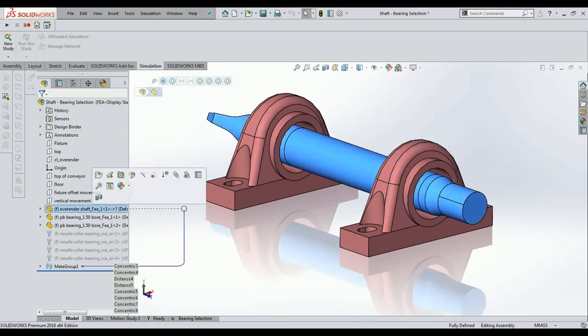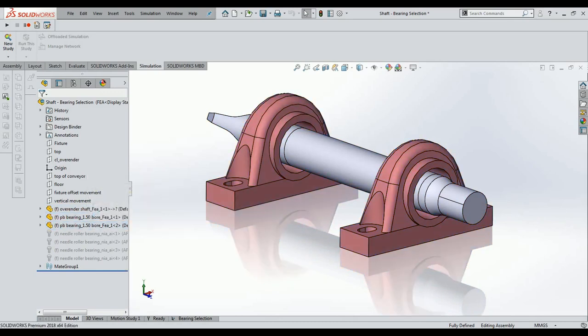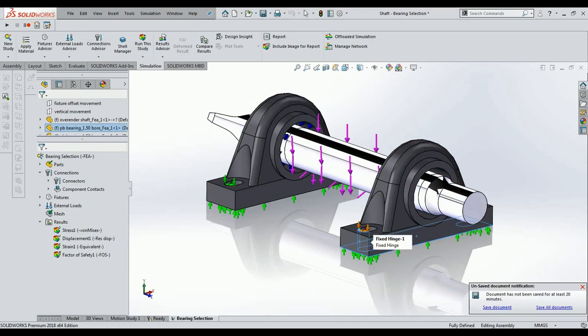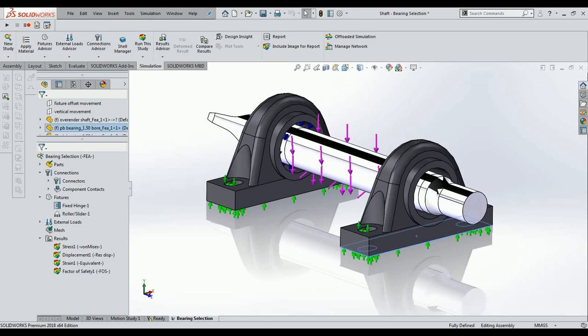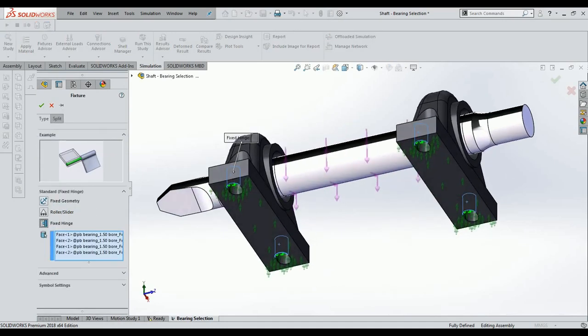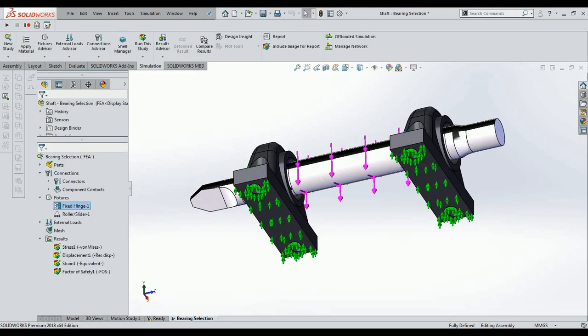Since it is a cylindrical shaft, I have introduced two different kinds of forces. The first one is the normal force, and the next is the torque. Obviously, everyone knows that a rotating shaft produces torque with respect to its axial direction. Here I have provided fixed geometry at the four corners, which are bolts fixed into the ground.